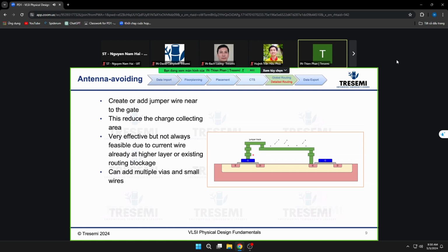They are not all connected at once. So we do the M1 here, and then we do M2, and then we do M3, right? If you look closely, the difference we try to make here is that we break the long wire. This method is called a jumper, essentially preventing the long piece of wire from connecting to the gate.